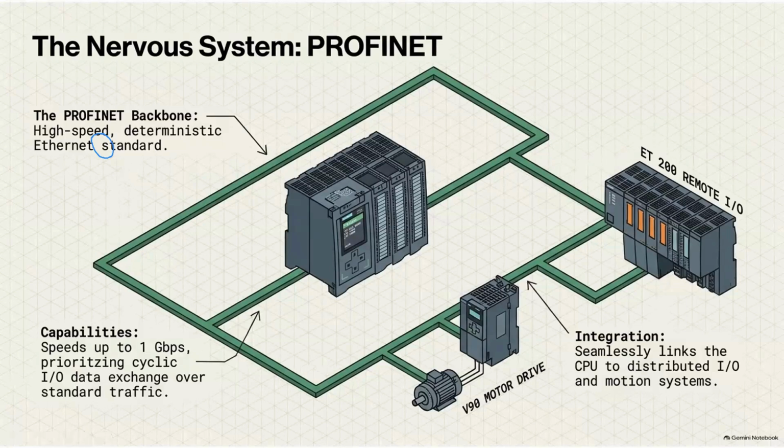If it is 230 volts, for example, and it could also be 440, let me explain. 230 means 230 volts. If it gives 150 volts, it rotates at 50% speed, and if it is 200, so whatever the voltage is, the voltage control is happening here with the help of the thyristor circuit that is present in this device.